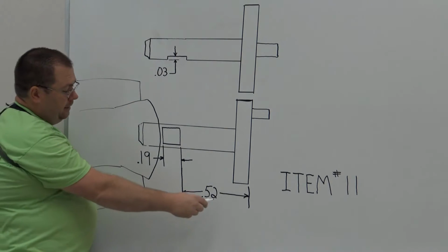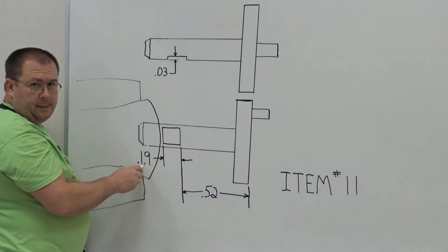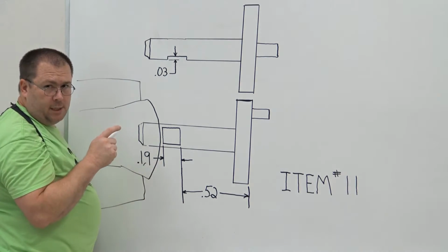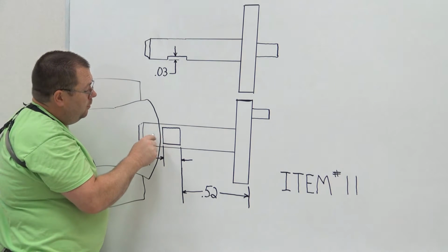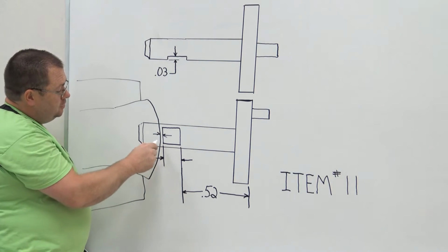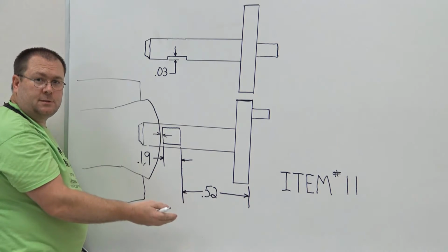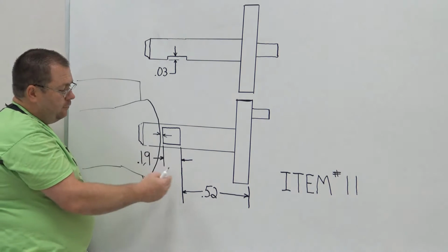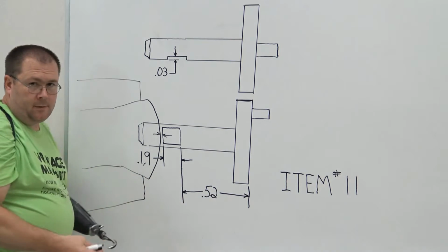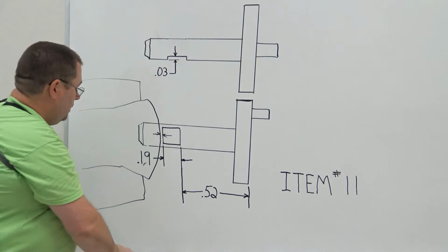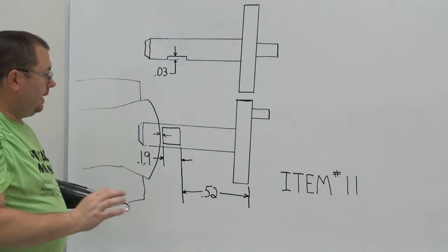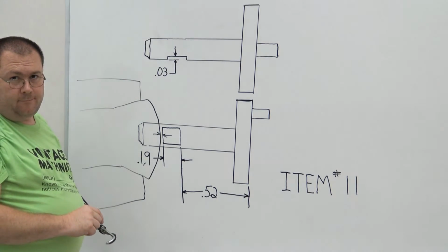So we've got this collet. I need 520 plus 190, that's 620, 710. Well, because you don't want to machine into one of Mr. Bryan's collets, we want some extra clearance in there, right? But because there's such a short distance here, I want to hold on to as much as possible. So if we have roughly 3/4 of an inch sticking out, or 750 thousandths, we should be in good shape. So now all this is sitting out there in space, but the shaft is stiff enough to handle our positioning technique, okay?